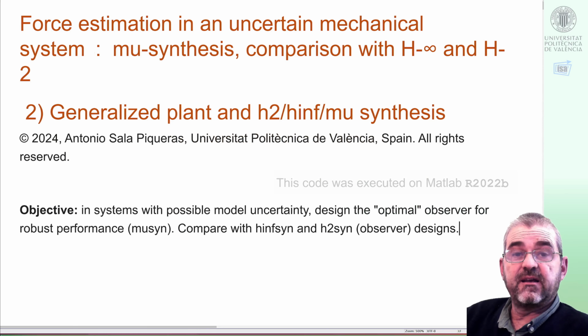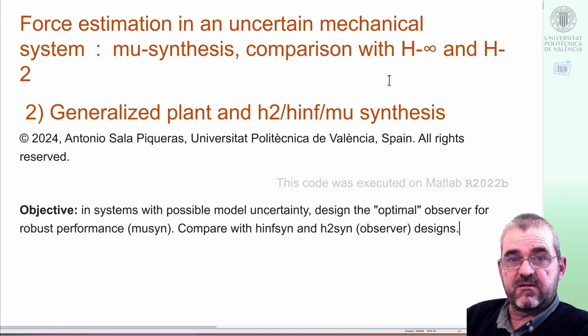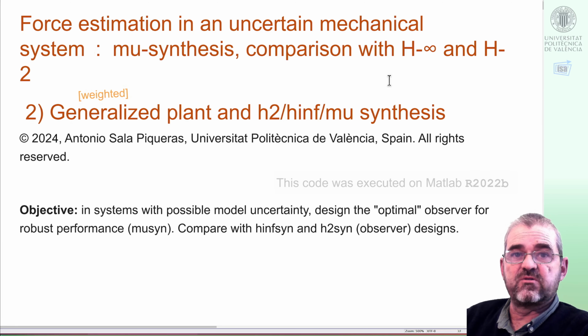I'm Antonio Sala, and in this video we will continue with the case study about designing a force estimator with modeling errors. In a first video we discussed the LFT uncertainty modeling phase. In this video we will build the generalized plant and will carry out H2, H-infinity and mu-synthesis optimization. Performance comparison in time and frequency domains will be left for a forthcoming video for brevity.